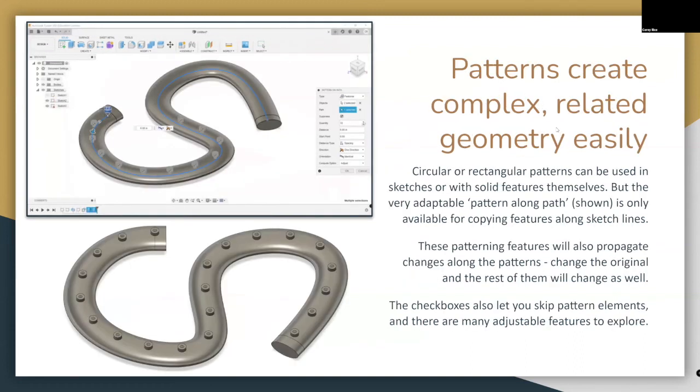Another one that's an advanced skill, but is really wonderful is the use of patterns. If you have a lot of repeated things, it's good to know how to make them and how to make them work. This is an example of a sweep, by the way. I've got an ellipse that I just swept along this line. So you can make really goofy, weird shapes with two sketches.